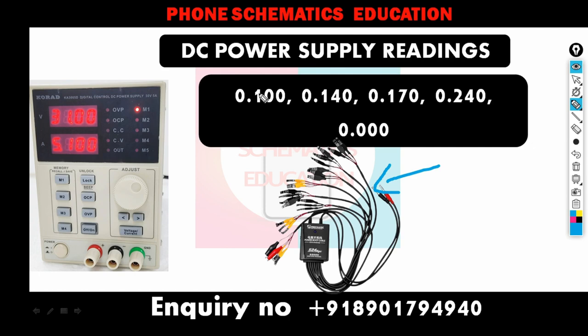But when you charge your battery, suppose the phone has a charging issue, which is why the battery dropped. When you charge the battery, it turns on. The issue is in the charging section, but you can work on the CPU, MMC, and the secondary lines. So also remember the boot cable has an impact.